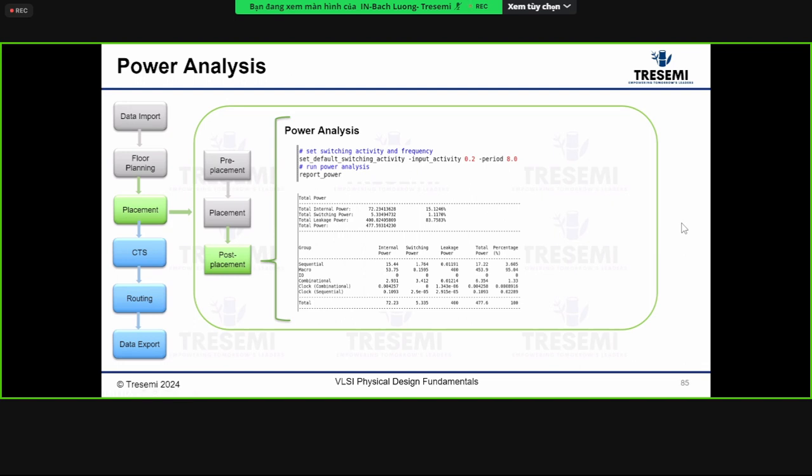But for switching, it's really depending on the switching activities on internal nodes. And switching activities is dependent on what you're simulating. For example, if you do a DSP or signal processing of your signals, or you're doing graphic processing, the internal circuitries, how often they switch, will result in how much power it draws.